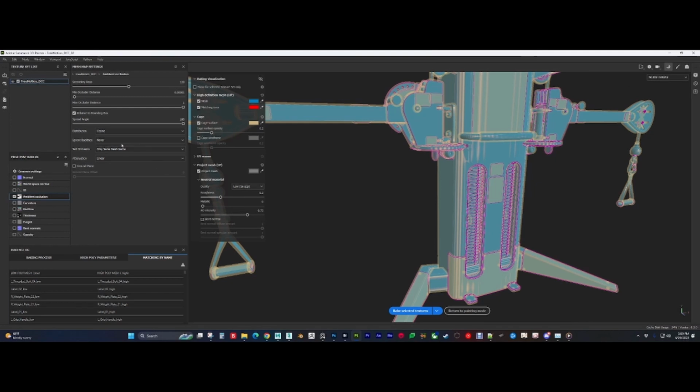So that's the two-step process I do. I make both ambient occlusion maps. I make one, export it out, bring it back in, make another, keep that, and I use each on specific parts of the model in my workflow.